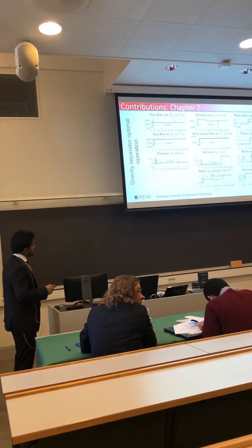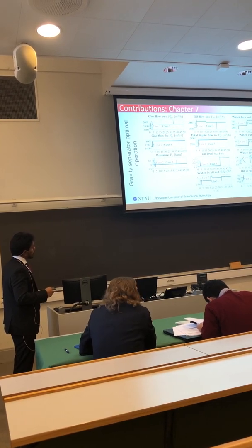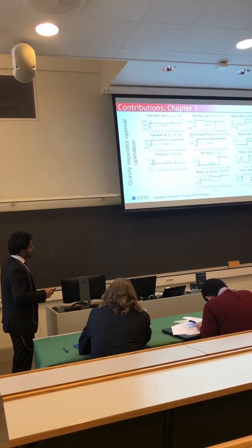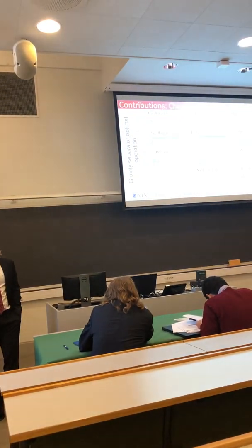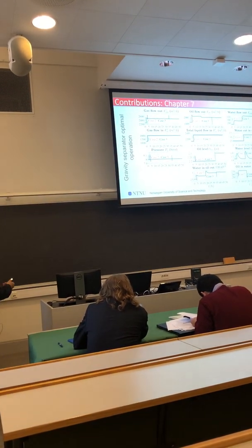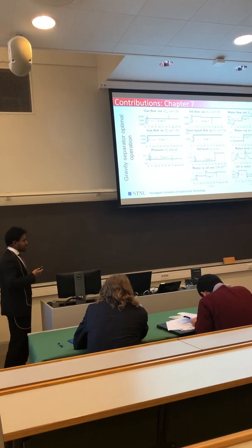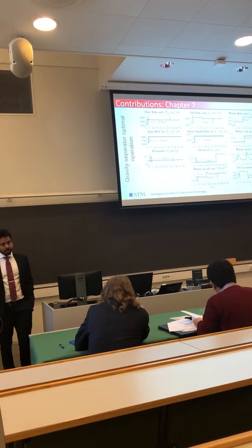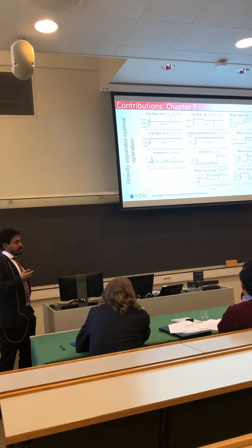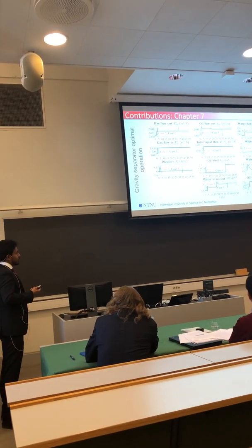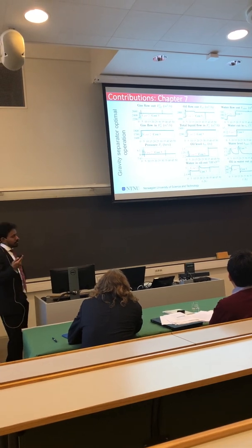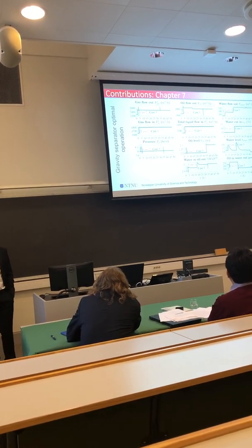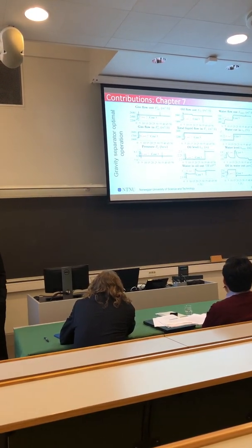And we see that the pressure is very tightly controlled, the oil level is also very tightly controlled, whereas the water level is let loose a little bit and the control is very slow. The reason is to make sure that the downstream equipment doesn't see it as a shock when there is a sudden disturbance change. Though disturbances in an oil field may not be of this step nature, we just demonstrated them in the work to make sure that the control system is also able to handle those specific kinds of situations.